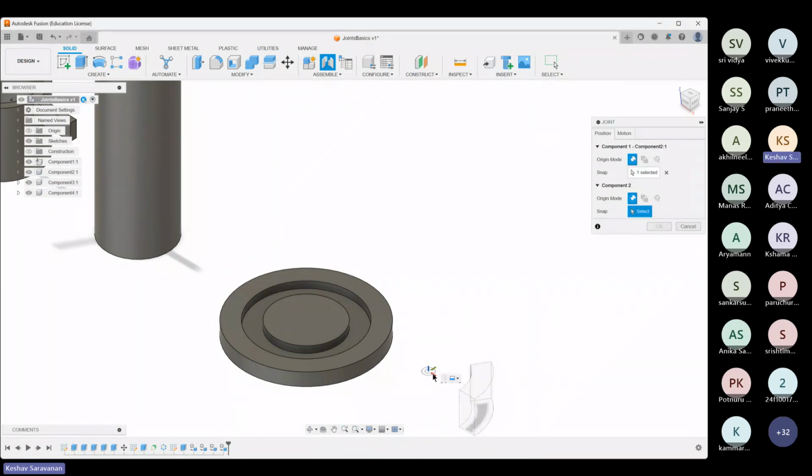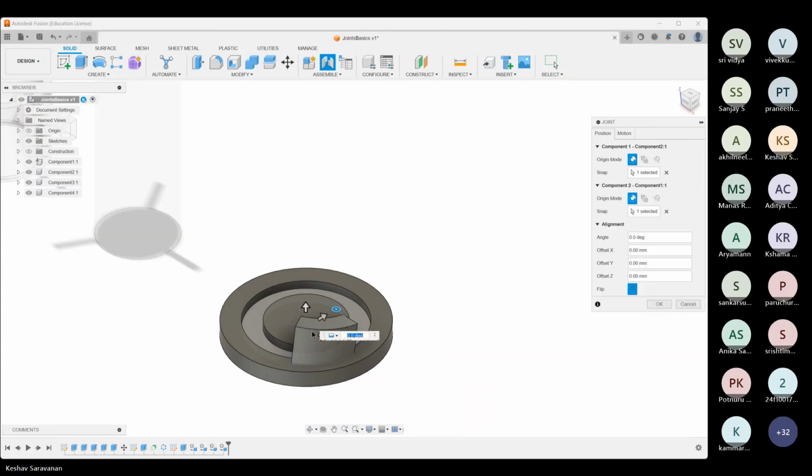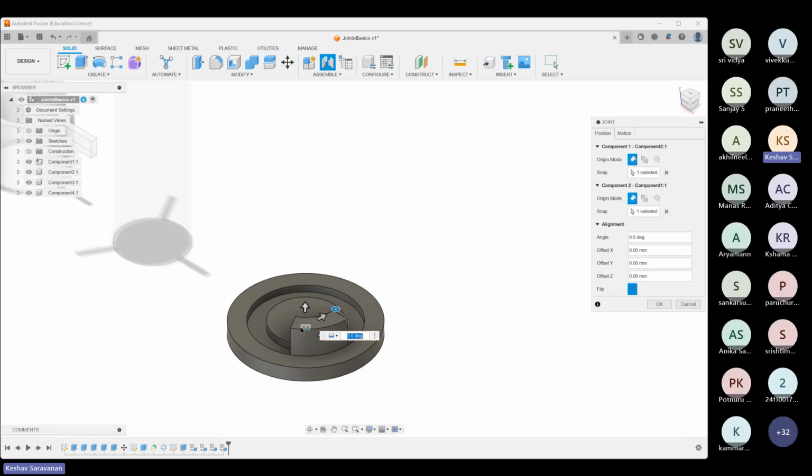I'm going to select that cross. That is number one. And then I want to select the center of this circle, but at the level of the depression. And to do that, I will place my mouse somewhere at the depression. Again, hold Control and then select the cross that appears. The cross is the center. And you can see it beautifully fits.